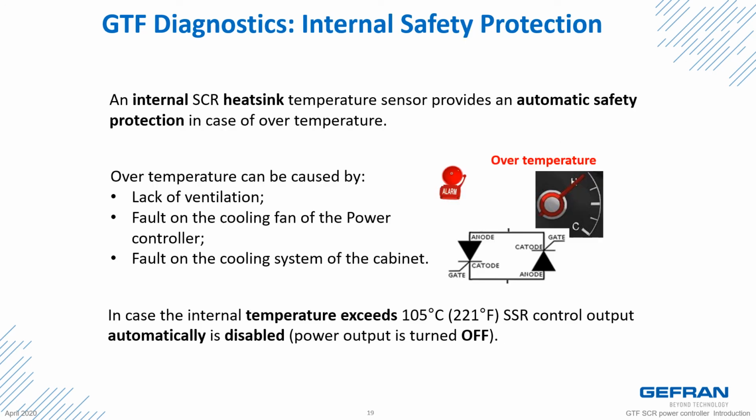Another benefit of the GTF Power Controller is the monitoring of the internal GTF semiconductor temperature. The GTF has an over temperature alarm that provides automatic shutdown of the power controller output if an over temperature condition is detected. This prevents the SCR power controller from destroying itself.